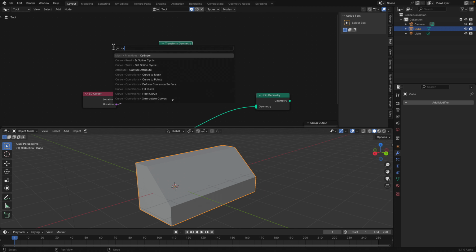The cool part about curve, when you draw it on the surface, it's gonna accumulate. So I kind of like this kind of effects. And same thing with the 3D cursor. Now if we use the 3D cursor and then snap it on the geometry, it will work the same. So now it's in object mode.